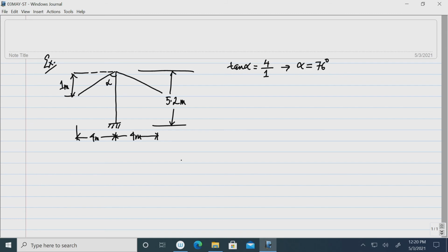Now, we take a level here, and suppose the apex is denoted by the symbol O and here the plane is A, at the free edge it is BB. We have to calculate load on the surface and then we use the physical interpretation of this integral expression to get the expression for n phi. Of course, one principal radius is infinity. So, n theta can be directly found out.